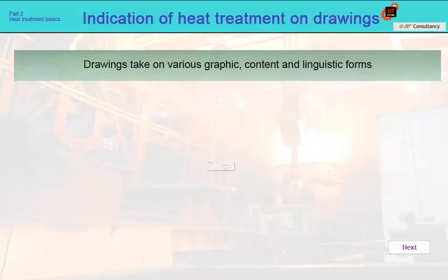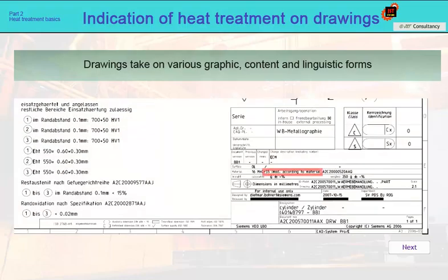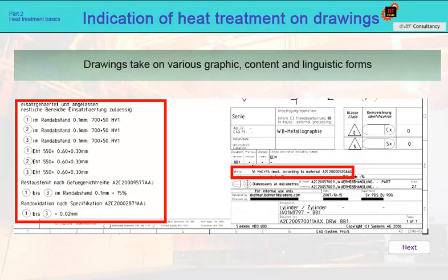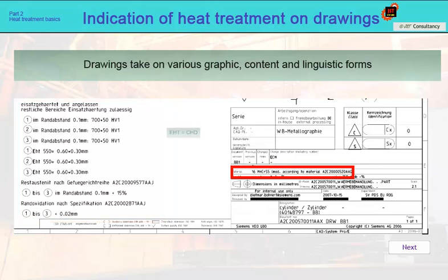Another example is a part made of 16MnCrS5 steel, carburized at defined locations to an EHT of 0.6 plus 0.3 millimeters and with the required surface hardness of 700 plus 50 HV1. It should be borne in mind that the abbreviation EHT is the original German DIN term for determining the depth of carburizing, while the current designation uses the term CHD.